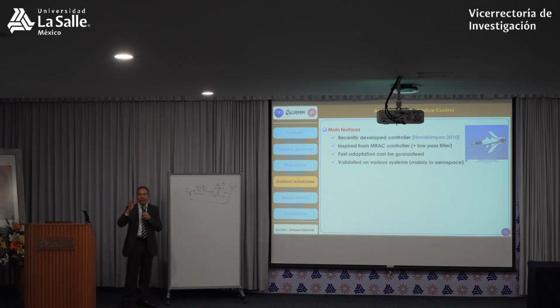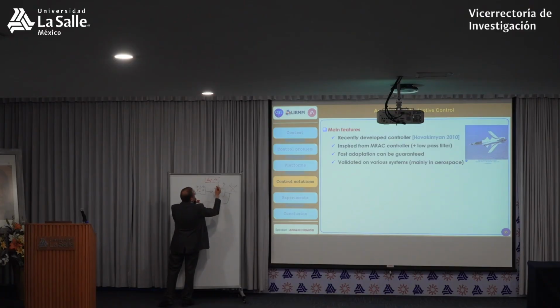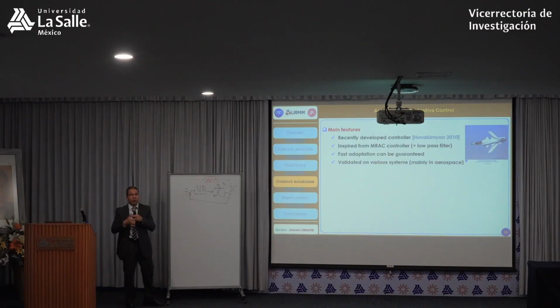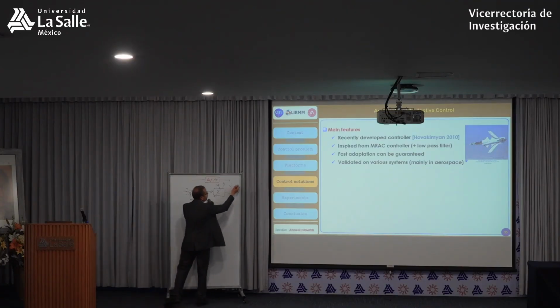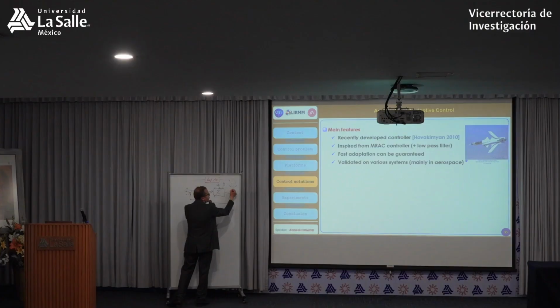The idea of model reference adaptive control is the following. First of all, you have to define what we call a reference model. What is a reference model? It's something that you put here. It's a mathematical model. Here, reference model, okay? And this reference model will be your reference, your desired dynamics, your desired performance. The performance that you defined, you put it inside. It means you choose your model such that you will have exactly the performance that you desire. It's defined by this model.